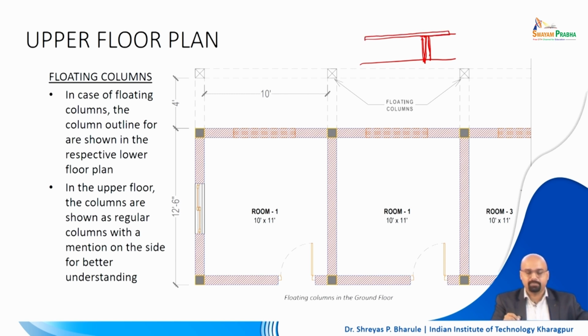This is your beam on the top floor, but your client also wants an upper floor which has a completely covered area, right. Then you will require a column at the end, but this column will not be supported at the lower level, correct. So, what do you do? You have a deeper beam here and you create a column on top of this,